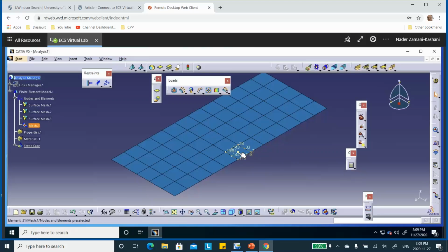Same thing with these two. This is the other line right there. So 129 on this side, 129. If you had not used the automatic mesh capture, then they will have different node numbers, and watch the previous video. You see that the outcome can be disastrous because they don't talk to each other.